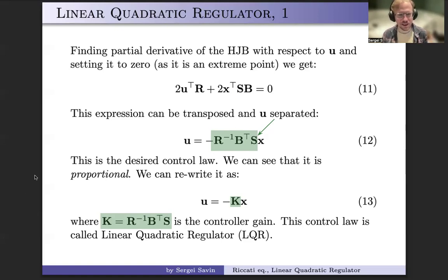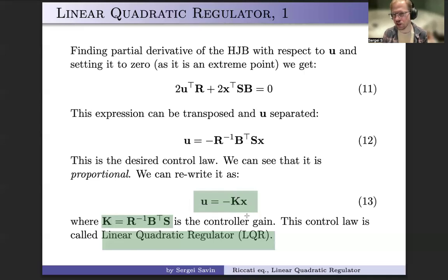All right. Now, by the way, if you use this control again, that is what is called LQR. So if you use this linear control policy and your gain is found this way, then it is LQR. What you're doing is a linear quadratic regulator. It is called linear because we consider linear systems, quadratic because of quadratic cost, and regulator is just the older word for controller.